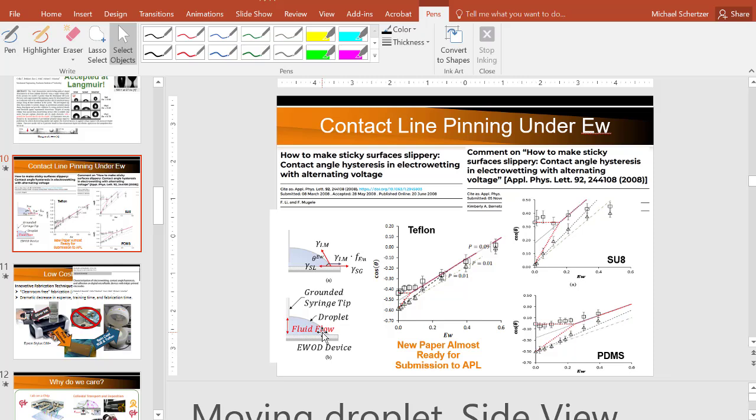If you're just putting a droplet down on a surface, you might get an angle that you're measuring, but you're not sure if that's at equilibrium, especially if there's a wide difference between the advancing and receding angles. For the experiments we've done on PDMS, there's a pretty reasonable gap between them. I can talk to you about ways to estimate the Young's angle, or the equilibrium angle, from the advancing and receding angles, if you'd like.